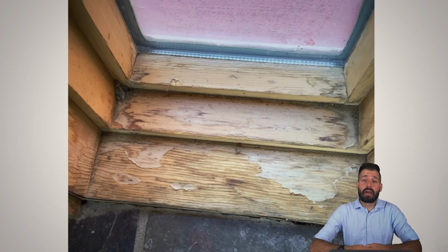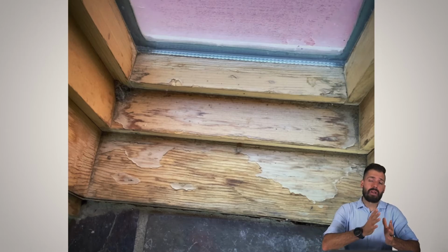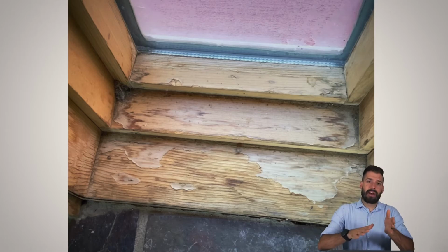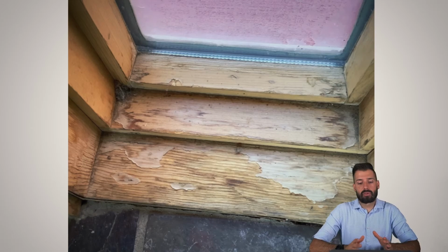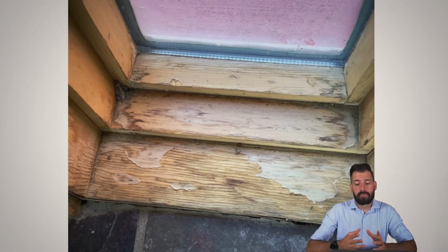Or it could be that we have a very hot inside house and a very cold window touching the outside, and we're getting condensation on that window. That condensation is coming down and getting water all onto this wood, which has caused all that damage. Basically, we need to figure out, is the water coming from the outside or from the inside? If it's the outside, there are some steps that we can do. If it's the inside, then we need to figure out why that's happening. Maybe we don't need to be running the humidifier in the middle of the winter, or maybe we need to make sure that we're putting our boots where they go, maybe getting a tray that the boots are supposed to go into.